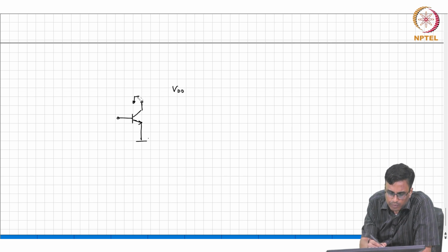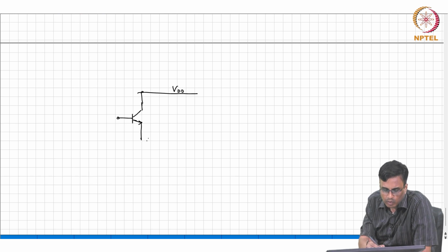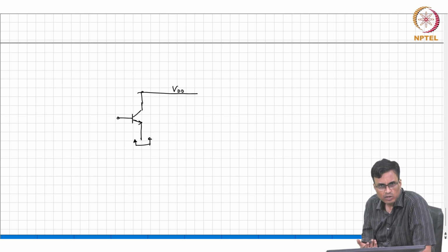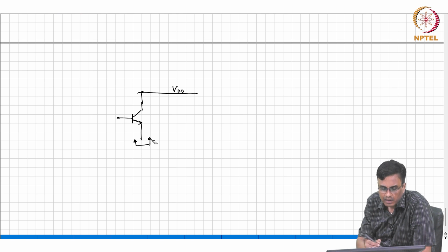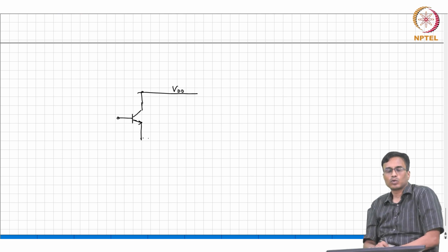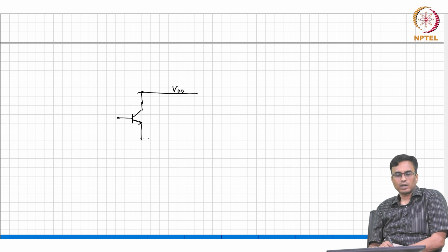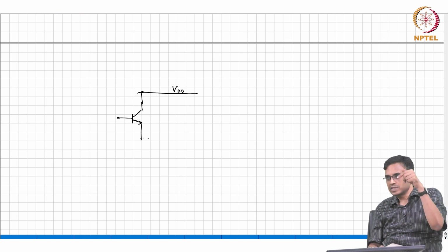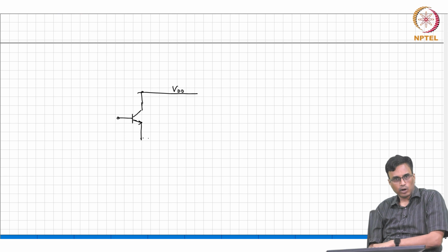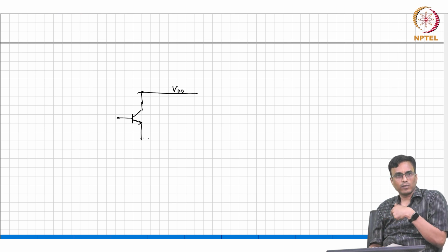Now if you say, okay, I am going to look at the current in the emitter, what comment can you make about the incremental output impedance here? 1 by Gm, it's actually a very low impedance, right. You want a current source so that you can push that current through a resistor to get a lot of voltage gain. But unfortunately our so called current source has a very low output resistance.